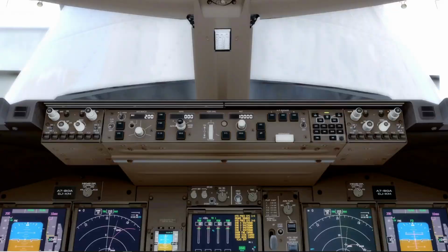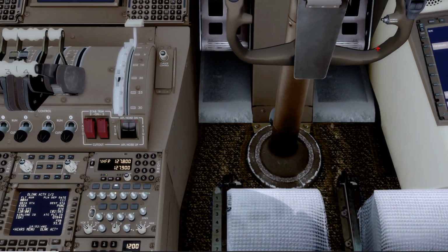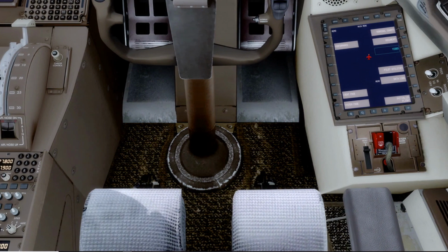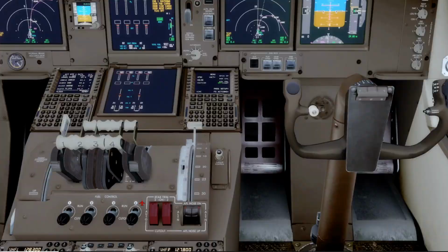And then you come down to your sidewall here, and we could check, if we can move over a little bit, our oxygen panel. And to check that, a little bit more difficult in the virtual simulator, but you can kind of do it. Boeing procedure is not to check the oxygen mask microphone, but some airlines do that. So if you were going to do that, you go to flight, which is right here. You go to speaker. We'd want the status page displayed.